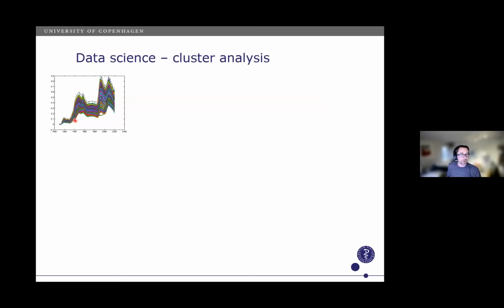is that I have piled up several thousand spectra during processing here. There's an NIR region here from 1100 to 2200 nanometers. What we can see here is an increase in water when I added water to the granulation, and then an increase in the baseline.